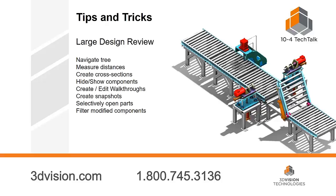And then the biggest thing you can do to improve performance, and this is if you have a huge assembly that you're not actually making direct edits to, but maybe you're measuring or doing cross sections of it, maybe making a walkthrough of a factory floor, right? That's a huge assembly that SOLIDWORKS is really never going to be able to load quickly. So use something called Large Design Review. That's an option in your File Open menu, and it basically only loads the entire assembly in graphics only. So everything's speed packed basically.